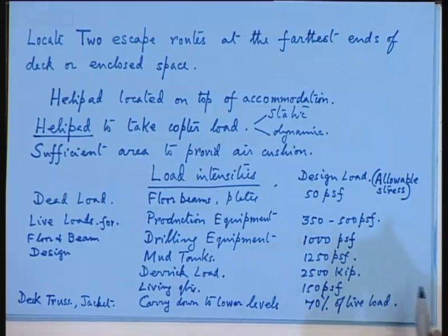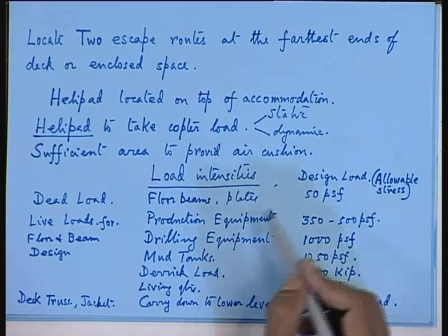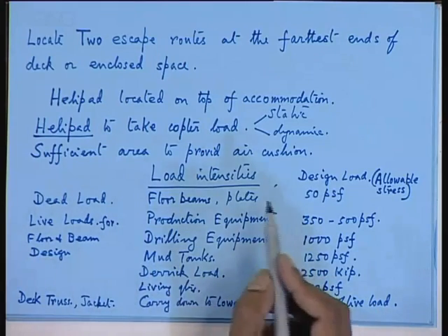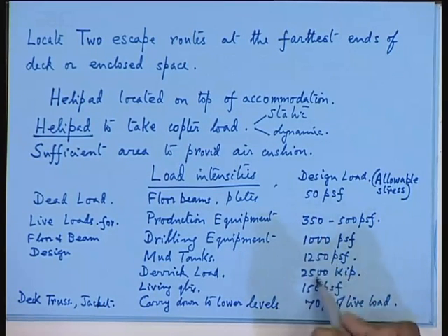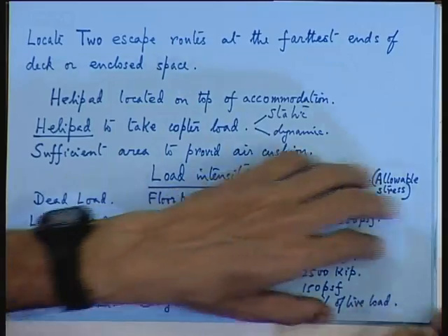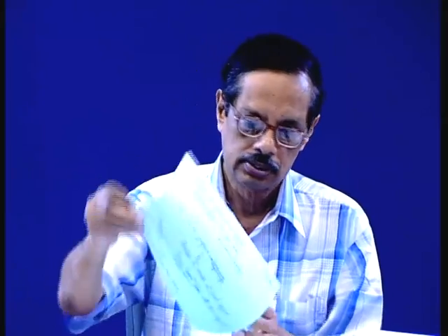What is mentioned here is that the deck load ultimately goes to the deck truss, and then it comes to the jacket, and after the jacket it comes to the pile. Once you go to the pile, then you have to take 70% of live load. So, ultimately these loads are carried down to the foundation, your pile is the foundation. So, this is one of the areas.